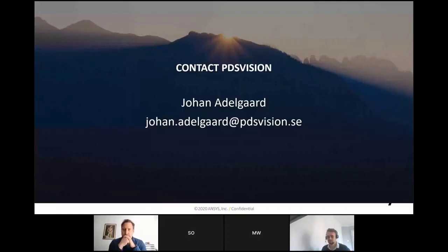Again, we have other packages, other systems. So MI Enterprise allows us to store all the different materials, and using the gateways that we have, a gateway for Windchill and a gateway for Creo, we can apply materials to parts, and especially with the Windchill gateway, that will create an object in the Windchill database that relates to a Granta material, and because it's in Windchill and we get links between the part and the material, you can do where used searches from within Windchill, but it's not an easy thing to do with Creo on its own. Okay.